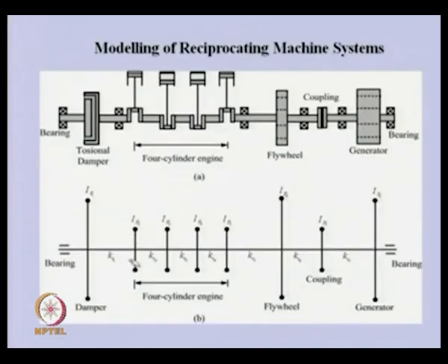So, these are the revolving masses of this engine, and whatever shaft is there, we can obtain an equivalent uniform shaft using the analysis of these cranks, either by experiment or by some kind of FEM packages. Once we have obtained this kind of equivalent revolving system, we already know the transfer matrix method will be helpful for analyzing such a system, or in subsequent lectures we will be dealing with the finite element method that can be used.